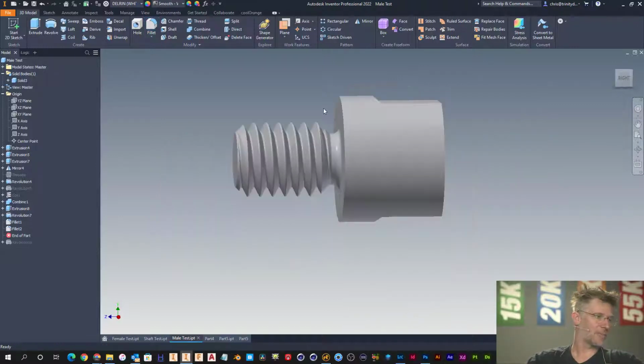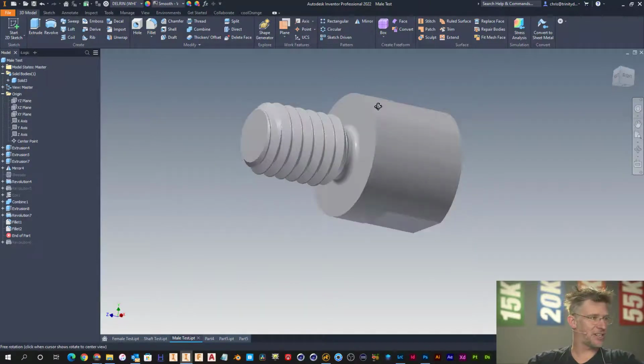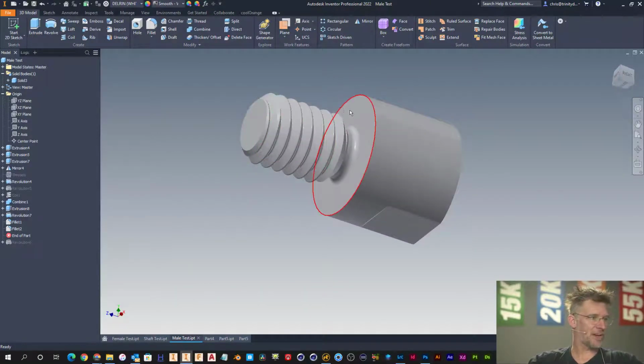So there we go. What you guys are seeing here is a thread relief cut on the top and a thread relief cut on the bottom. The top one is 0.01 total, smaller than that top surface. That'll give us a complete line. And the bottom relief cut is 0.02 larger than the tangent at the valley of the male thread. And then if you guys wanted to, you could throw a fillet on here. Where did my window go?